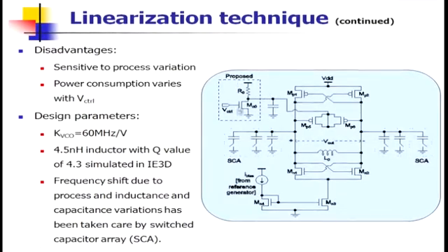generator, and the charge pump output, that is the filter output from the frequency synthesizer block, is fed to a common source amplifier, and then it goes to a capacitor. This capacitor is used because if there is a VDD and there is some kind of transient, it is called the supply bounce or the ground bounce, some transient might come from the VDD, so that might go into your varactor and that can cause frequency fluctuations. To avoid it, you have used a capacitor so that the large transients can